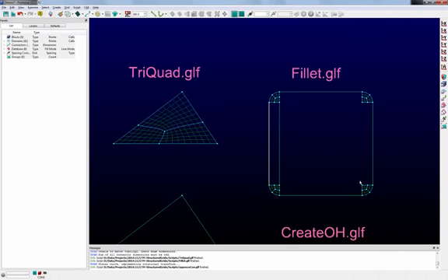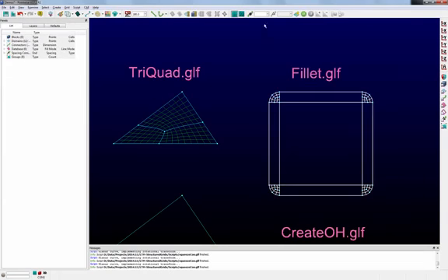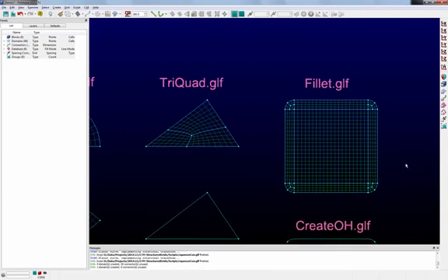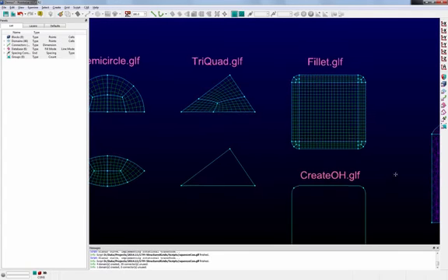So we simply highlight the connector, run the script. I'm just re-executing with Control E here. And then create this internal topology pretty quickly. We can then highlight all of these connectors, assemble the domains. We'll need to create that inner part as well, highlight those connectors, create domains. And you can see we now have a very good, highly orthogonal domain here in the center.